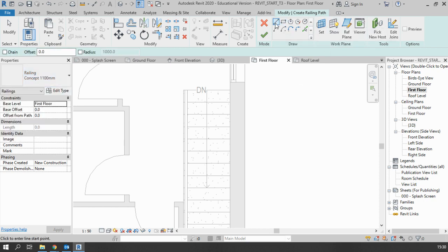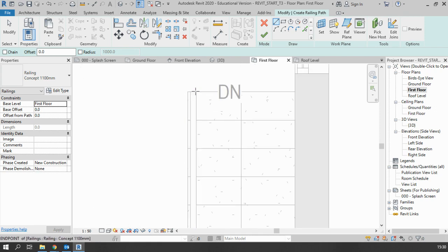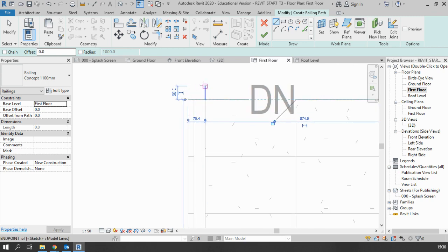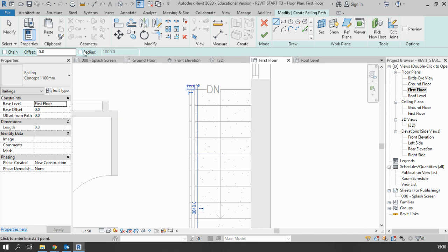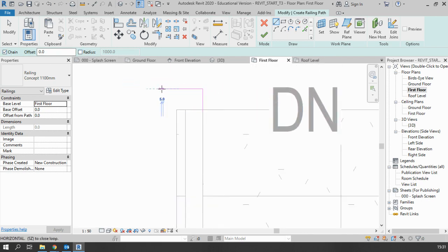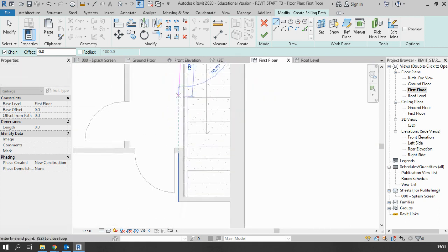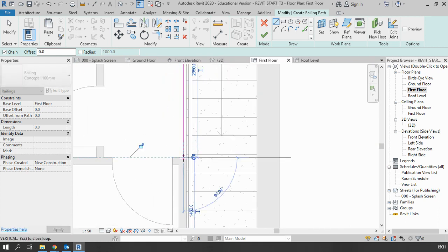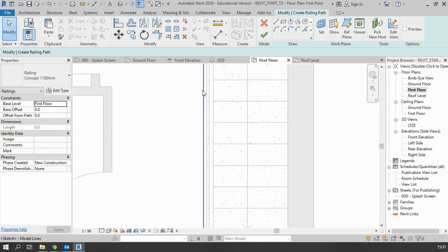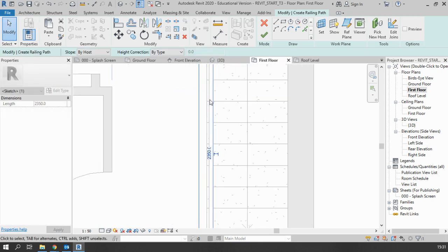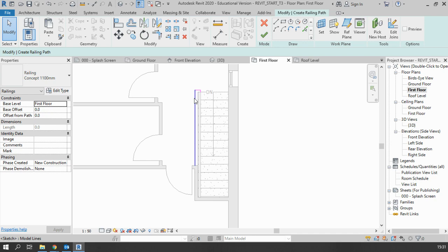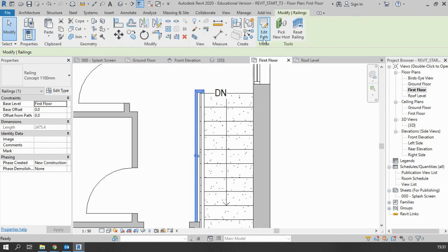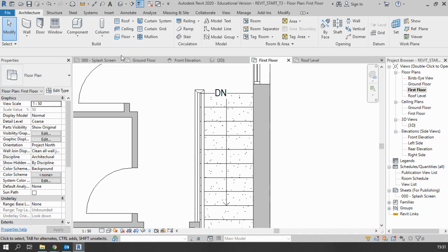Again, you can use any of the tools. I'm just going to click the line tool. So I'm going to start here. I'm going to go up a bit and then along. So I'm going to start there and then go along for a bit. Then I'm going to come down the way. And chain should have been on, and would have been a bit easier there. But yeah, just make sure chain's on if you are doing this kind of stuff. Yeah, you can put that in all the way to there. Click escape once you're done. It might need to be pushed a little bit slightly more this way, just to take it off the edge. It's fine. Once that's done, once you've got that line, it's perfect, no gaps in it, tick it, and then that should now give you a rail.